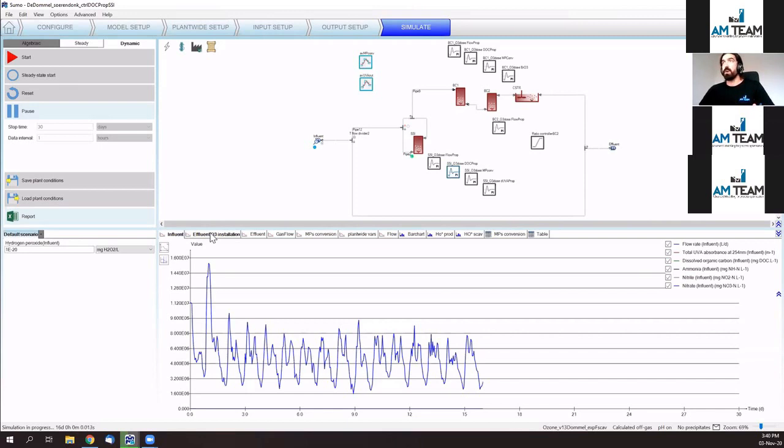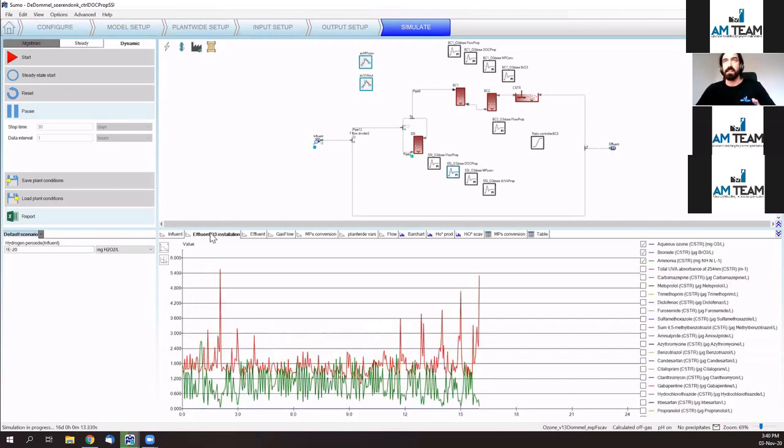And with this model, you can look at what is happening inside your installation. Actually, what is the effluent bromate, for instance, at different points. And what is interesting to see, which Wim will mention again later, is the ammonia influence on bromate, because of the formation of monobromamine and dibromamine, which is sequestering bromide ions. This is an interesting detail because it really influences the bromate formation, meaning that the control of your upstream installation, the wastewater treatment plant, has an impact on your bromate formation possibilities.